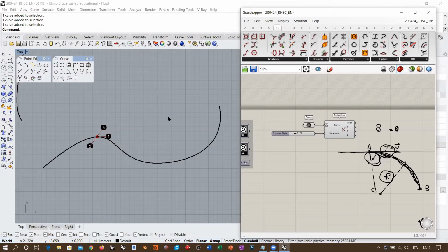So it's a complex set of information that you must take care of at the same time when you are drawing something. So yes, you can create class A surfaces in Rhino when you work with aerodynamic surfaces, for example. You just have to know how to do it, and you have to know how NURBS topology and NURBS geometry work.